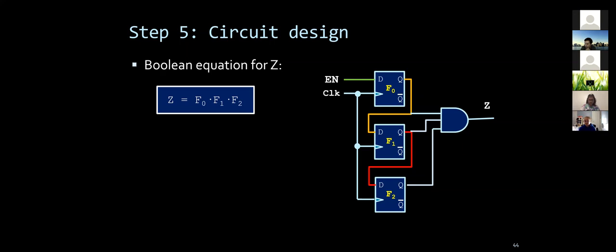And then the second question is, so we'll look at each bit of state and see how each bit is affected by other bits. More or less this, yeah. So essentially it's the same as in a regular truth table, right? You need all inputs, right? You just convert a more complicated finite state machine into the static table, right? And it can be quite large, but essentially it's the mechanism that works. Okay. Any questions here?